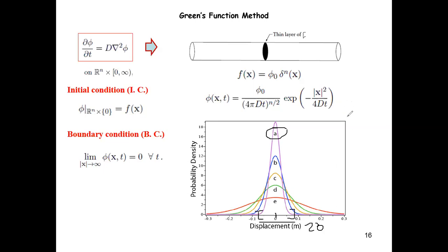Yes. Okay, so my question for you is this: sigma also roughly tells you the distance, how far the carbon has diffused. Now I want you to compare this equation, the solution, and tell me what rough expression for sigma you have. Again, sigma is the distance of how far the carbon has penetrated through diffusion. If you compare this to the equation, what is your sigma, roughly speaking? We don't have to be precise. Is it the term in the exponential? Yes, but exactly what is this term?